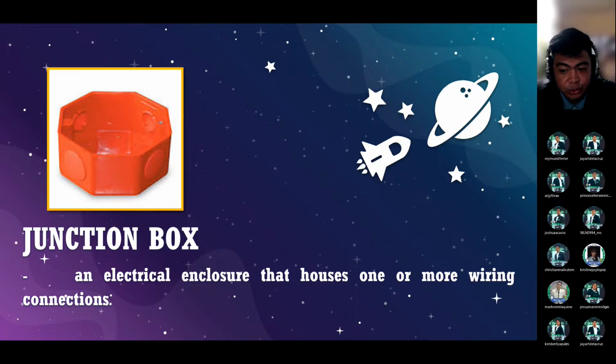When a junction box is used for every electrical connection in a building, it is much easier to locate and repair any electrical problems that come up. When some connections are made without a junction box, such as inside wall cavities or in a hidden ceiling or attic location, the likelihood of future problems increases. Every electrical connection should be inside a protective box, what we call the junction box, that is easy to find and access. So, do you understand, class?